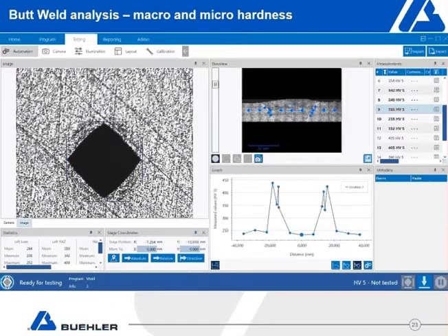And as an illustration, once you've done the test, this shows a match where your base metal, your weld, and base metal are of equal hardness, but the heat-affected zone exhibits a high hardness value as illustrated there. So potentially, if you do routine weld evaluation, these are areas that should be of concern when working with this kind of weld.